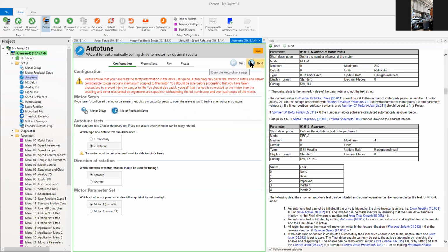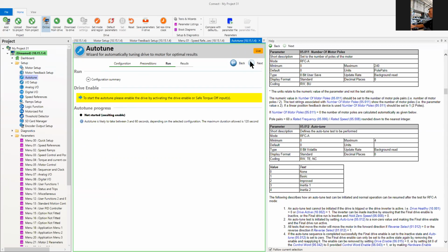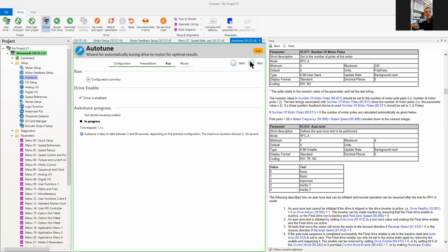Again. Hopefully this time it should be fine, and it doesn't go that fast, because it went over speed. That means the PID parameters are too high. Oh, maybe the parameter for the encoder. I've got to double check the parameters for the encoder.